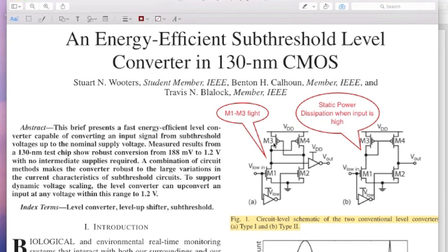For small voltage differences, it's okay. 0.9 to 1.2 or 0.8 to 1.2, you just upsize the NMOSes and deal with that and solve the problem. But in subthreshold, it doesn't work well. So then you ask, how do you weaken the PMOS? There are various ways of weakening the PMOS. This is one way, where what is being done is a diode connected PMOS.